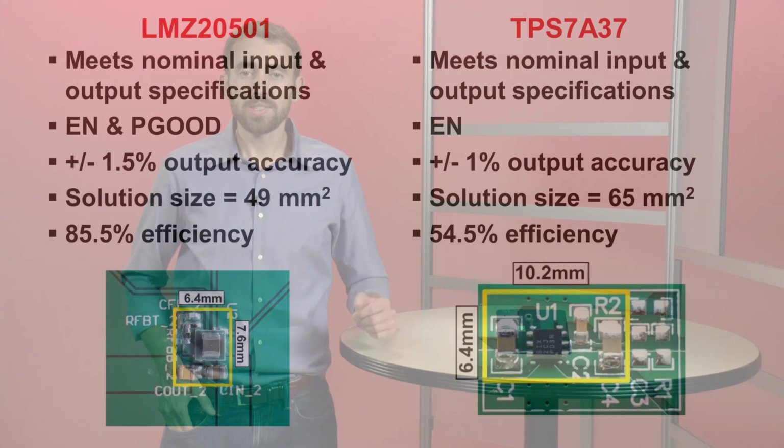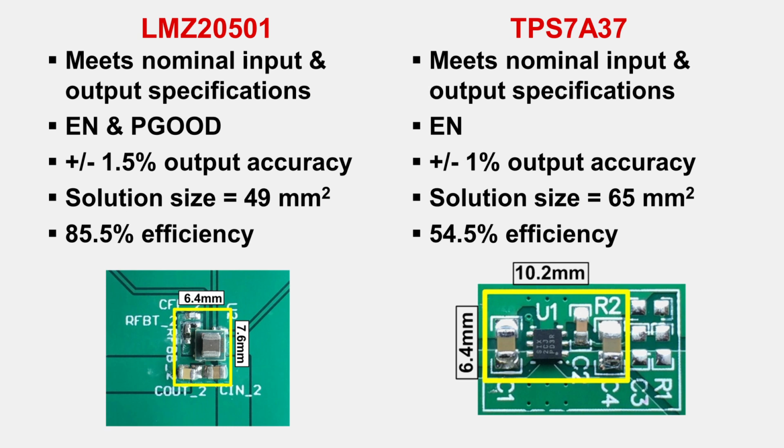When we compare the devices for this application, you can see that both solutions deliver the nominal application specifications, and they both have similar features, though the nano module includes a power good pin. The difference between the two is that the simple switcher solution size is nearly 25% smaller than the LDO. So the better fit in this application is again the simple switcher nano module. So this is just a sample comparison of the pros and cons of both the LDO linear regulator and the integrated simple switcher nano module.